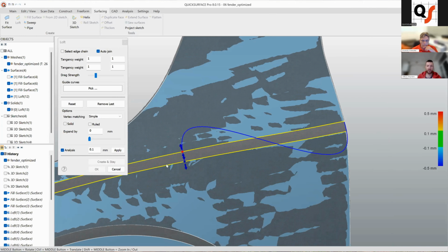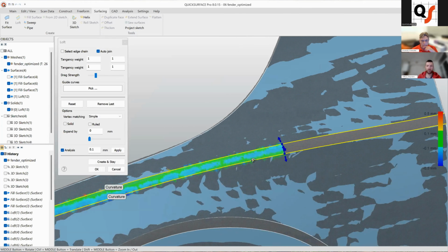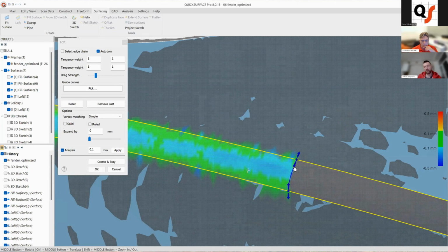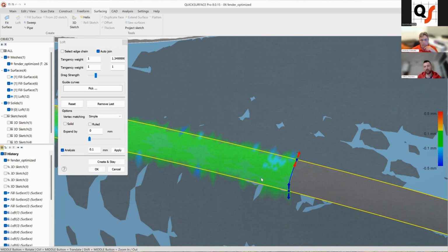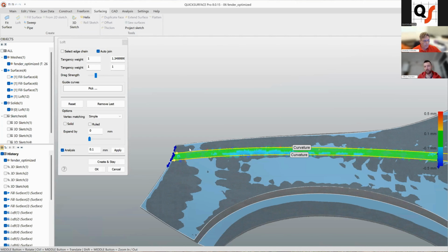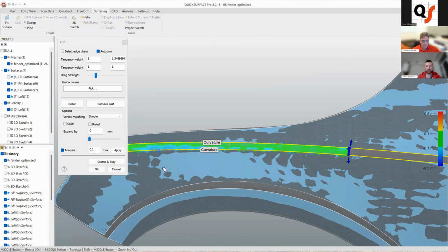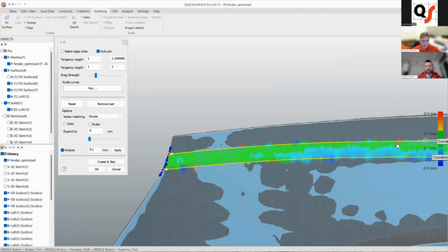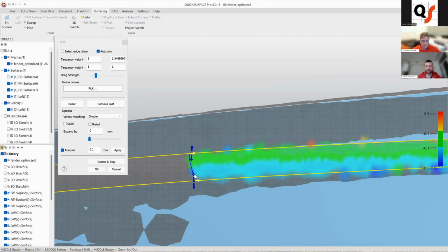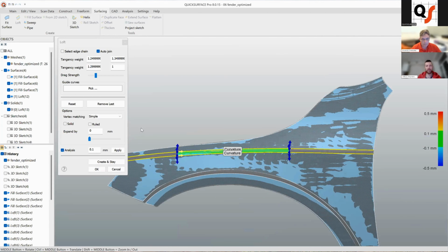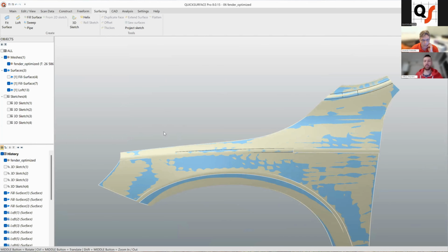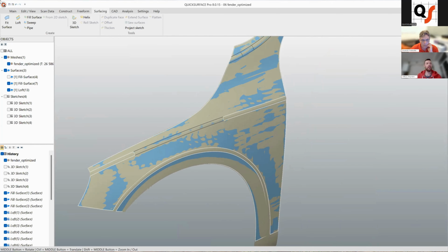pull our control points to a region where we want to change our tangency. This, or probably you will want to create this from like 3 patches. Something this way. And just reposition them as it's better for you. So this will be shortly about lofting.